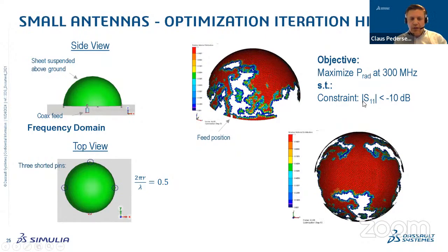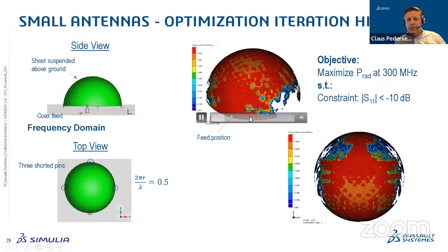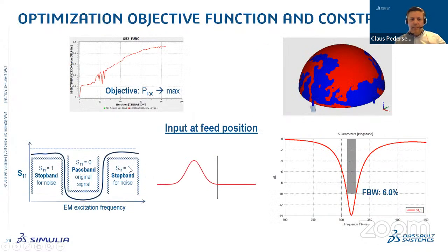I'm just going to shortly explain what that is. We see here the conduction gets optimized. And that means that for some frequencies, when you come in with the current, you want this signal not to pass at all, so you don't get any noise in. And also for high frequencies, it should get nothing through. And then in one given band, you want a lot of signal going through. So that constraint we have for the minus T dB, this is the one you see here. And this one is fulfilled also in the reconstructed design.